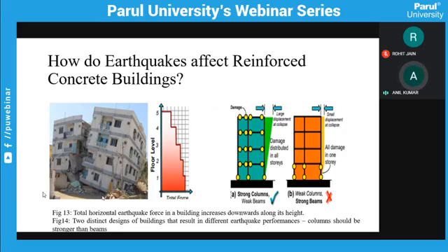What we have to follow is that the flow of inertia forces to the foundation should be direct. There should not be a break of forces. Walls and columns, we know, are the most critical elements in transferring the inertia forces. But in traditional construction, we can see that floor, slab, and beams receive more care and attention during design and construction than walls and columns.